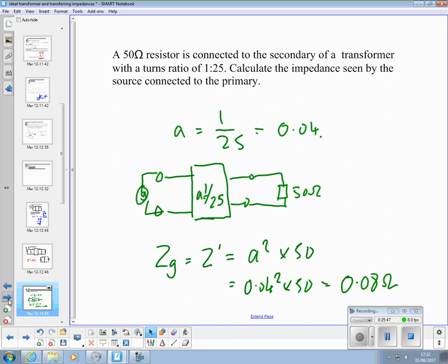Sorry, that's the impedance of the generator, so that side's going to have more current. That low impedance there is going to cause more current to flow in this side than in the actual secondary, which is right for a step up, because voltage goes up, current goes down. I'm just trying to show you how you can notice whether you've gone slightly wrong by knowing whether that transformer steps up or steps down.